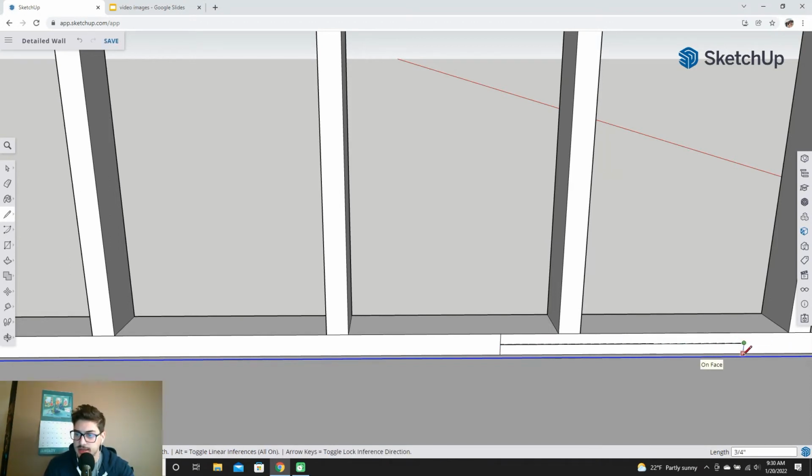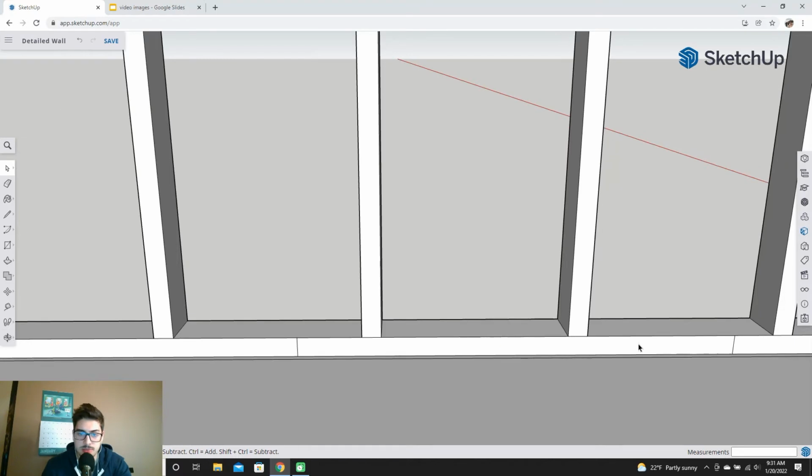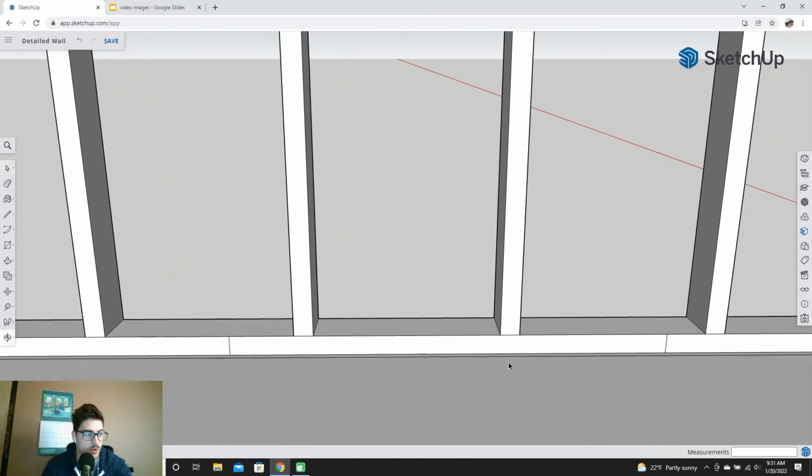But let's go ahead and say from that midpoint that we made, that means we're going to add 17 inches to either side for a rough opening. And then we're going to mark those edges. And then we're going to clean up everything in the middle. So we don't need these anymore. Not really. And I'm going to put in the new studs before I remove the old ones to show you what we're doing.